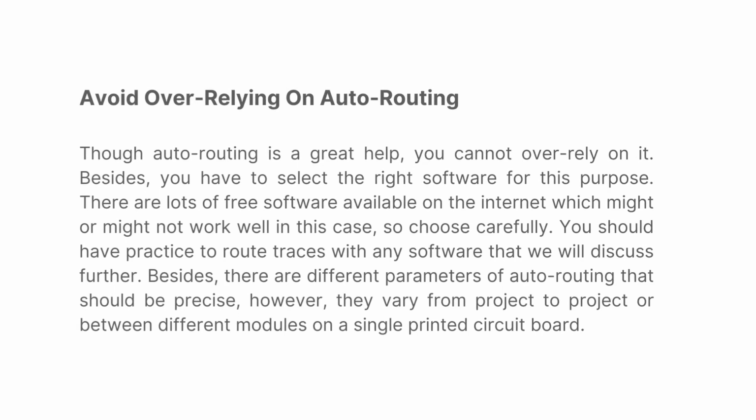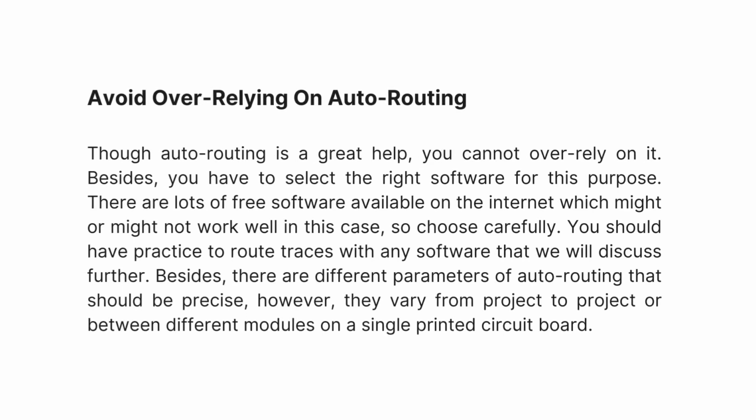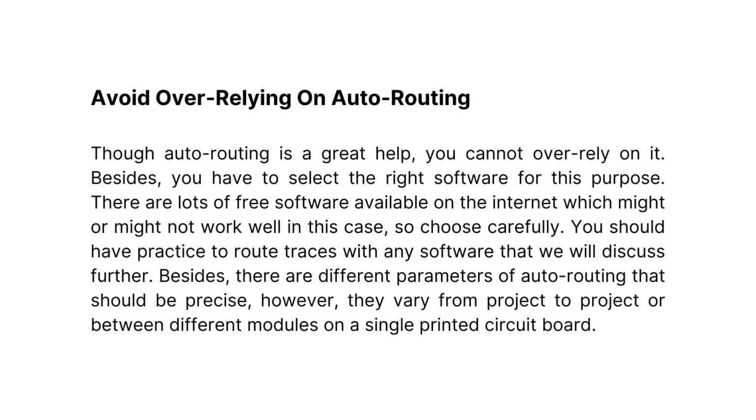Avoid over-relying on auto-routing. Though auto-routing is a great help, you cannot over-rely on it. Besides, you have to select the right software for this purpose. There are lots of free software available on the internet which might or might not work well in this case, so choose carefully. You should have practice to route traces with any software that we will discuss further. Besides, there are different parameters of auto-routing that should be precise. However, they vary from project to project or between different modules on a single printed circuit board.